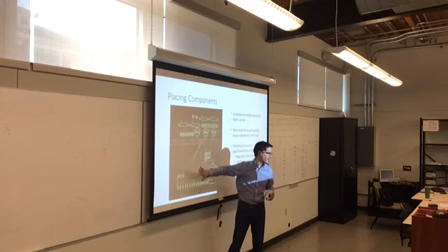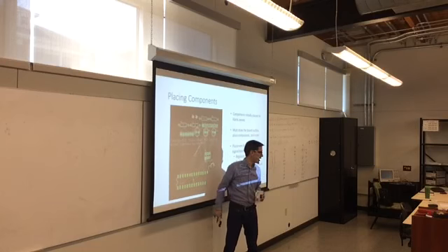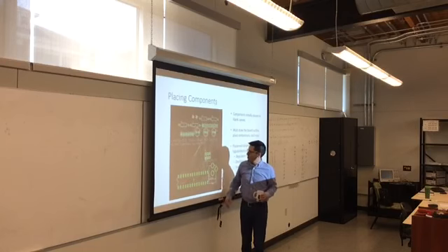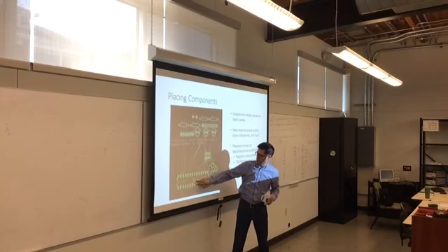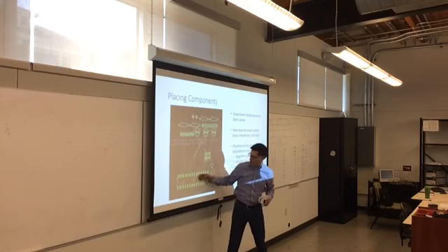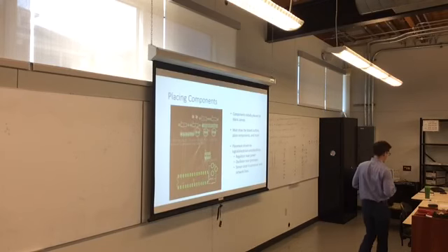So this has a lot of connections to this side of the chip. I would take this and I would put it right there. That's where it should go. Your programmer, a lot of the connections are over here with one or two on the other side. Maybe you can route them down over here. Like, find channels for all of the nets to go.